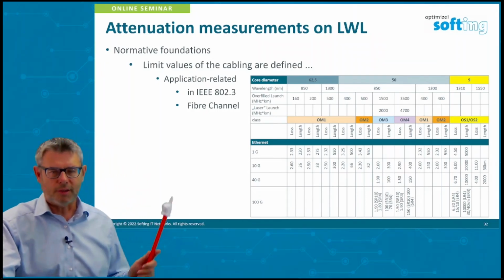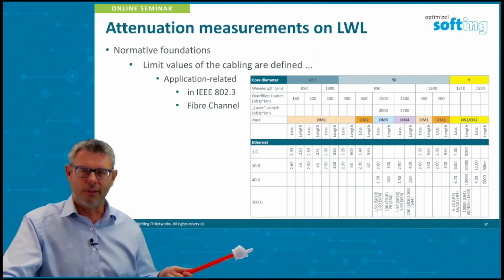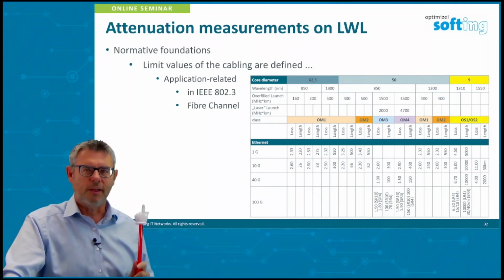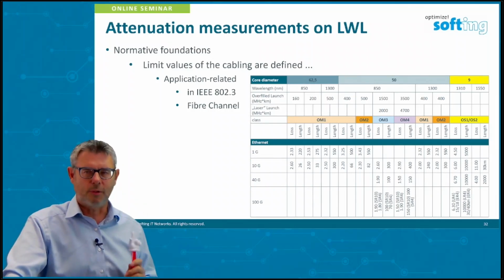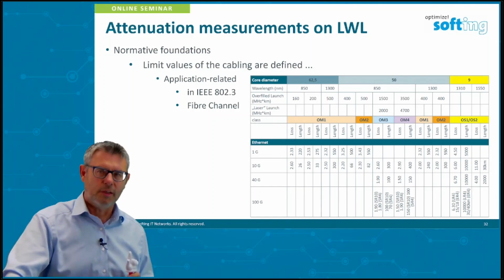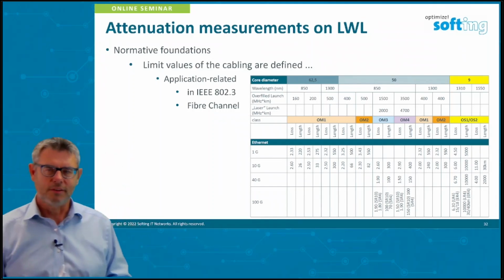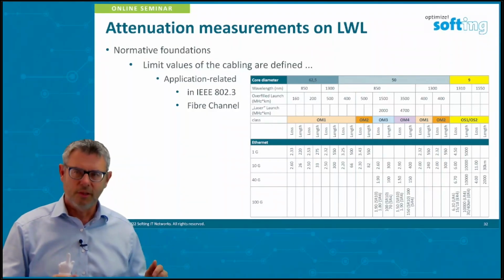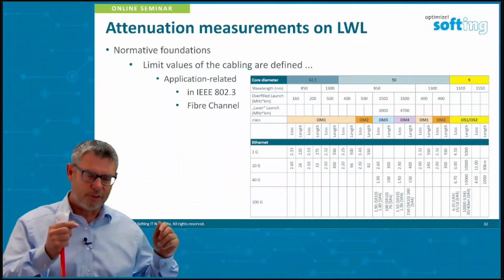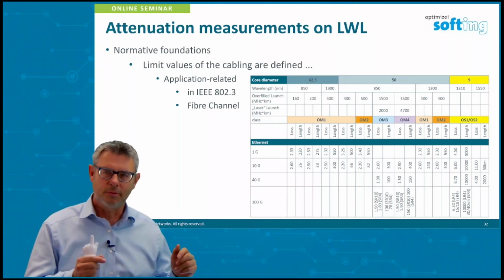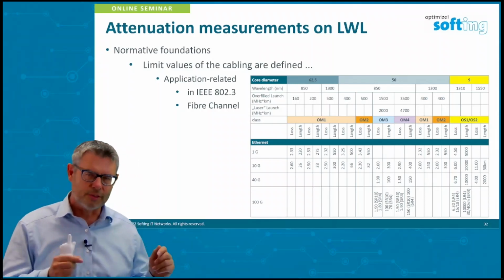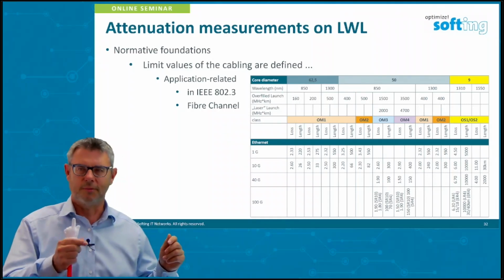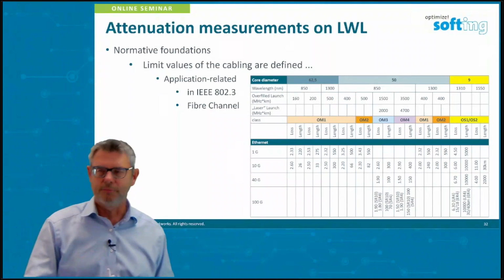Okay, now we are moving into doing measurements. We defined already how to get limit values. Now let's come into measurements. There is a basic rule when doing fiber optic loss measurements. You never ever connect the cable under test directly to the measurement instruments. Even when it's a channel and it will fit very nicely to the instruments, don't do it. We always use test reference cords to do the connection to the fiber optic link. Okay, that's the golden rule.